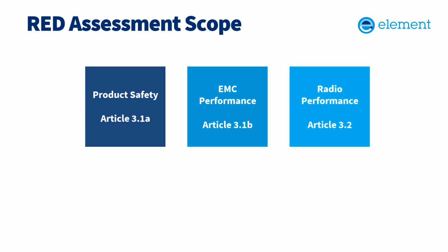And then the last one is radio performance. Radio performance to make sure that it's on the right frequency, occupies the right bandwidth, power levels. It might have some receiver tests, which I'll talk about a little bit later on as well. And it's all to do with, again, stopping harmful interference through the characterization and measurement of the radio characteristics of the product itself.